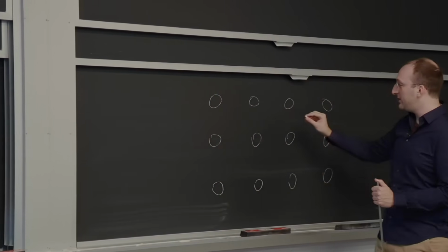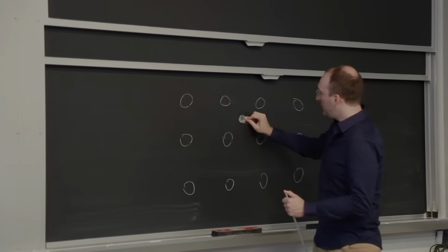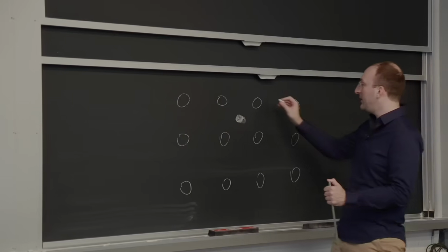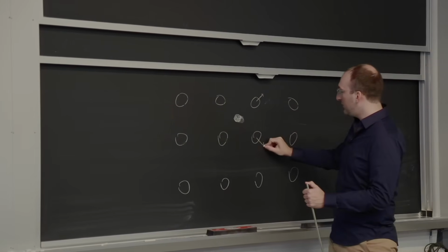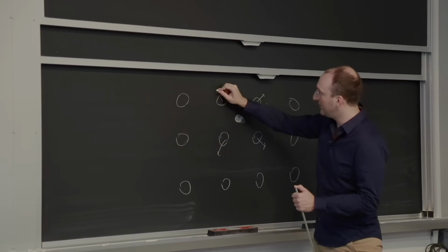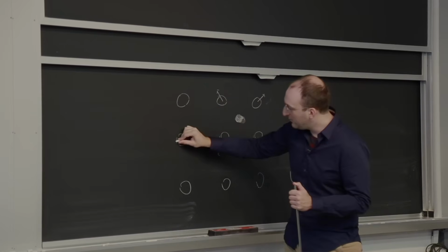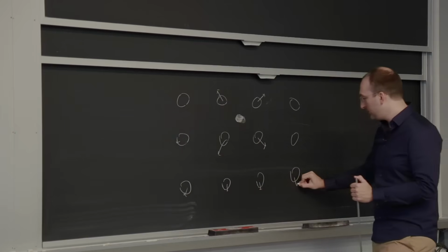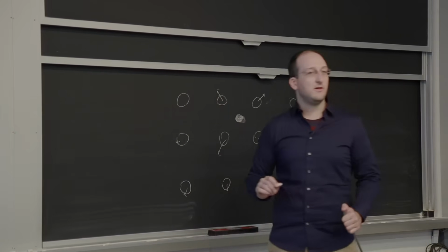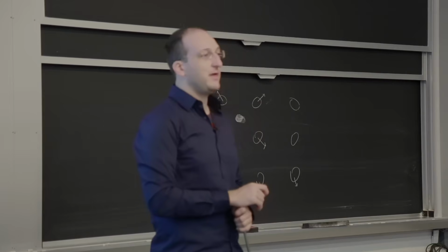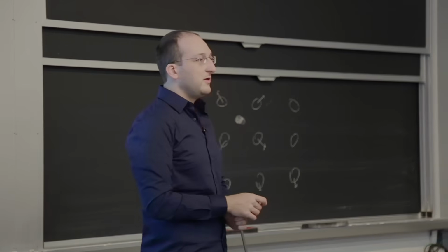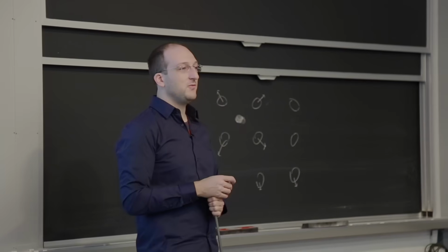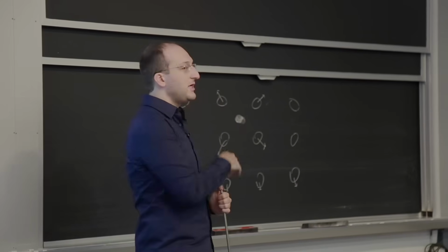Let's say I want to shove an interstitial atom in here between these other atoms. Well, their electron clouds are going to repel, and it's going to push all the nearby atoms away by just a little bit. And these ones might push the other atoms away by just a little bit, stretching out the lattice or adding some compressive stress wherever that interstitial is. But then how would it move? What's the biggest barrier it has to overcome to get to the next adjacent location?